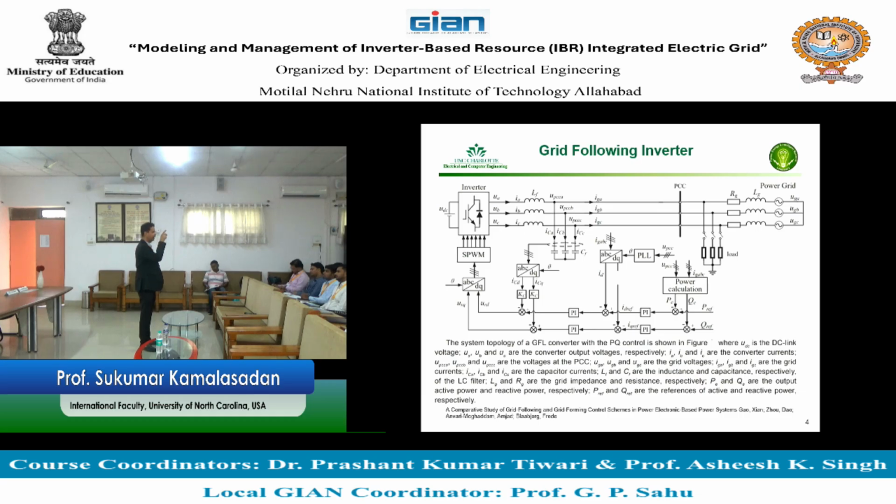So when you say V angle delta, V angle 3 degree or 0.4 degree, that 3 degree or 0.4 degree is not the 120 or 240. It is not that 3-phase shift. It is a change from that. That is basically the delta. So you look at that delta. I stand there, and when I look at the other 2, they are at 240 and 120. I see they are at 240 and 120.